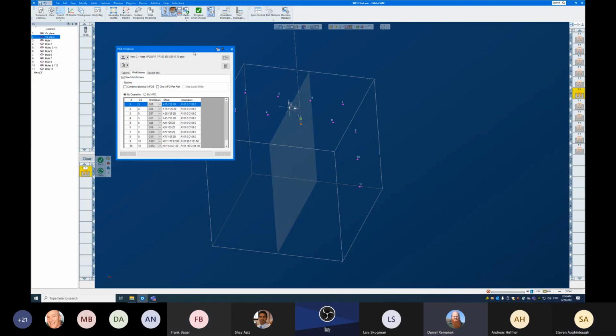And the reason is, I'll talk a little bit about this. It's actually a fundamental problem with turning. Turning assumes that we have a constant center of rotation. And when we tilt the B-axis, we're actually changing the axis of rotation, and so none of our turning toolpath works. So that's the reason that you can't do that specific thing. If you kept the axis of rotation constant, you could tilt the tool within the axis of rotation. But that is not what your case was doing, certainly.